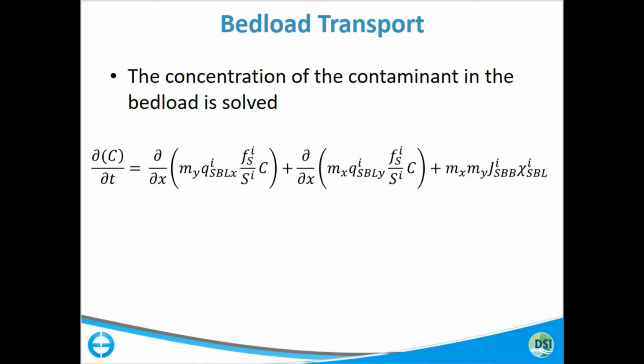EFDC Plus has changed the way toxics is transported in the bed load. We manage a bed load concentration, just like any other unit volume or control volume. So I have a bed load concentration and a bed load sediment mass, and I have a bed load toxic mass in each square meter.